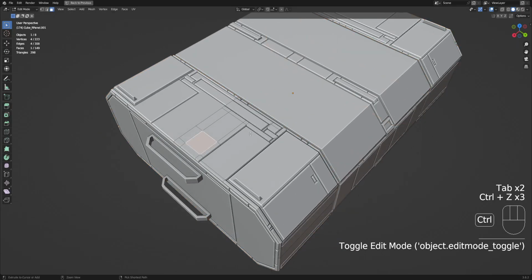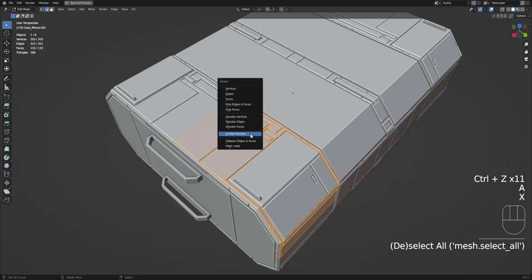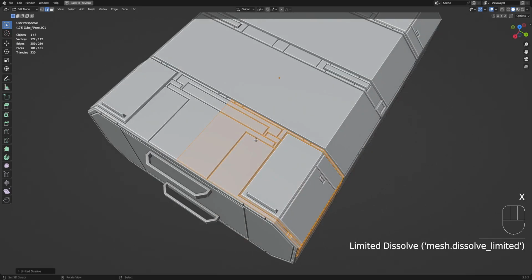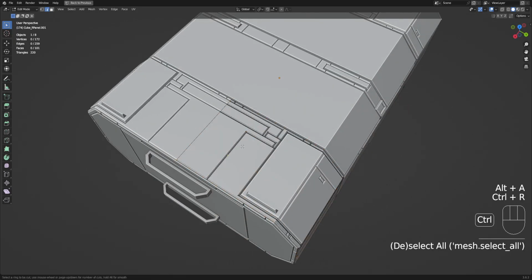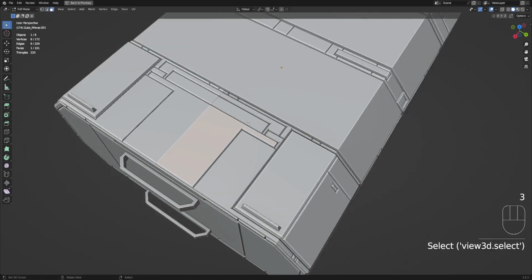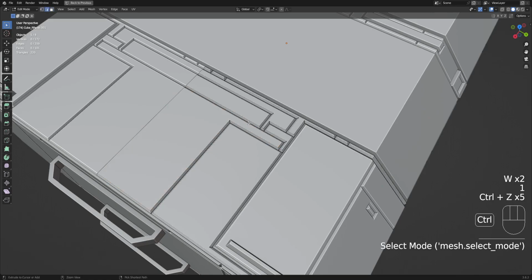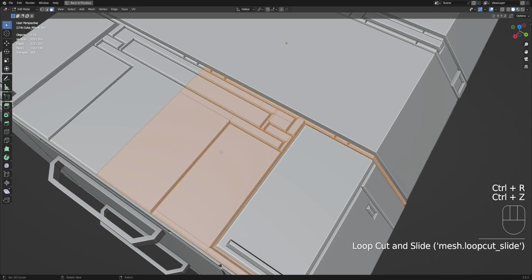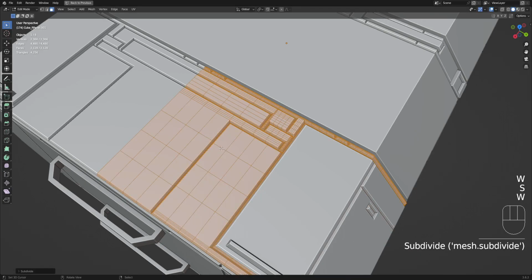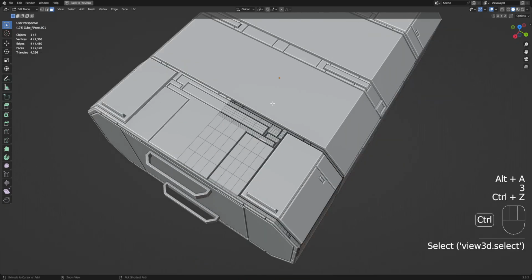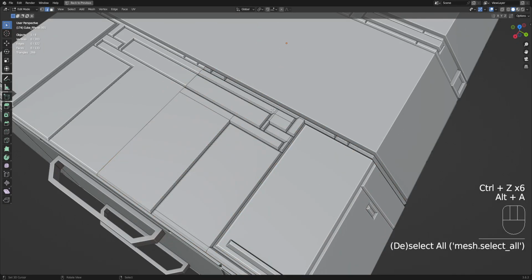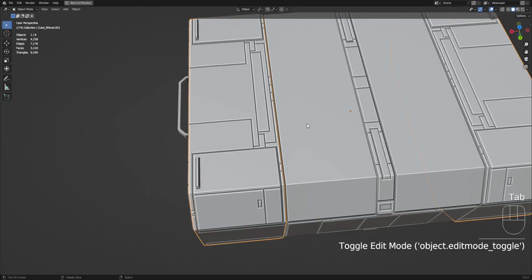begin extruding shapes from that, versus, for example, if we limit the solve and give this back to an n-gon constructor, you can't use loop cuts on it. You can only do loop cuts and subdivide on a quad structure, which give you more faces to play with. So I think that's the main advantage when using a quad structure like this.